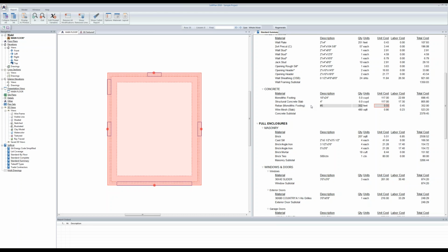So if I generate another project, it will once again give me both types of reinforcement, the rebar and the wire mesh, and it would again only give me 2 rebar lengths per edge of my footings. So what I prefer to do is not include those as changes to the specific project, but I want those to be the defaults.